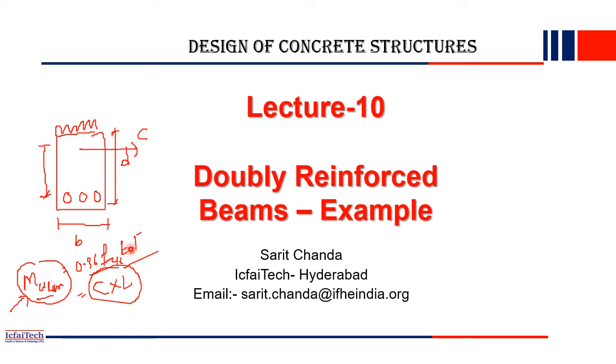So what is the next alternative? We can provide steel reinforcement at the compression side also, because concrete cannot take much tension force, whereas steel is very good in the sense that it can take an equal amount of tension as well as compression. So we can add additional reinforcement at the compression side, like here, to increase the moment capacity.